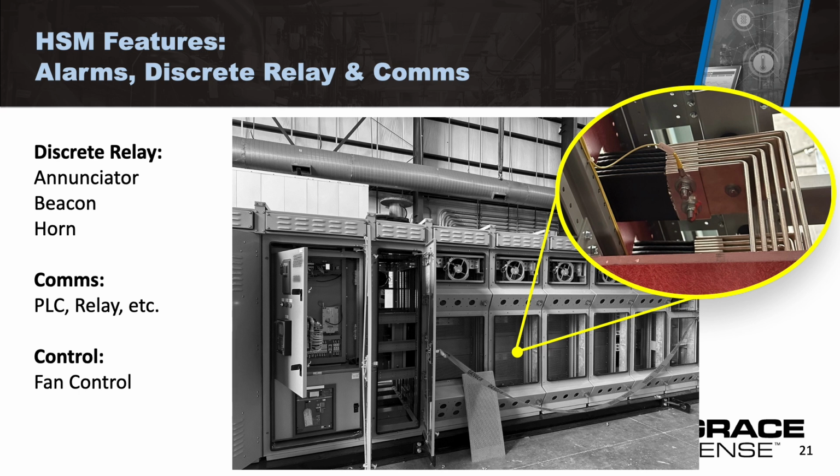And I've seen other people do other things with the discrete relay. For example, they put it into an annunciator or a data concentrator, some method by which to get an immediate alarm when it hits that high level, which we'll talk about in a minute, but are settable based on your particular circumstance. We also have folks who just take the data and integrate it into their HMI, or even little flashing lights on top of, what are they called? Beacons? Yeah, beacons, and horns, to alert people.